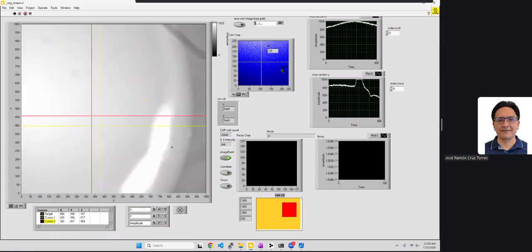This is also a big piece of potential improvement for the image correlation algorithm, because its general robustness is pretty important. For example, if you're trying to closed-loop move to some position, and all of a sudden it latches onto something else completely, it's going to screw up your closed-loop control. It'll try to move in that direction, and it has caused some issues before.